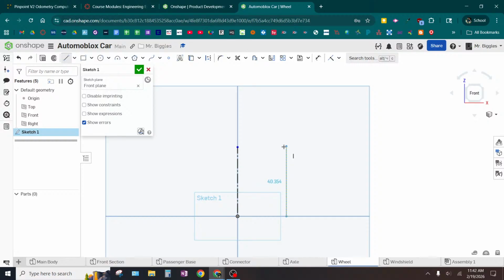In fact, I think I brought this up, that my recommendation most of the time is that I prefer to fillet with the feature tool rather than with the sketch tool. Okay? And we've talked about why that is. So this is actually this inside. I know it's curved at top and bottom, but we're just going to do a straight vertical line.